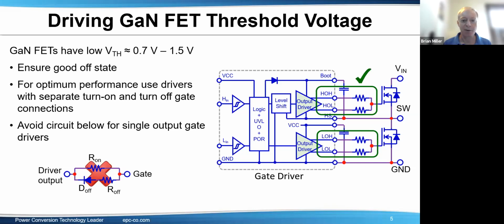But for EPC's GaN FETs, it's not good. The best thing is just to adjust the resistor values, and that'll take care of it. Adding inductance, even from a small bead in the gate drive loop, just hasn't worked well in our tests.